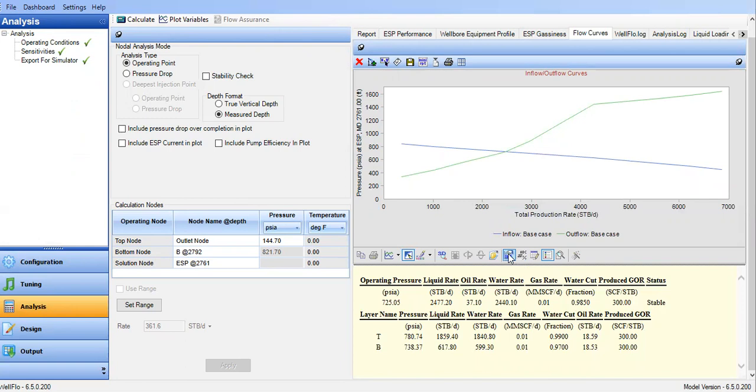Okay, so by combining the two reservoirs, we get improvement in oil rate. Previously, if I'm not mistaken, the oil rate was 23, because you have water cut of 0.99. And after you combine them and the new reservoir has lower water cut, you get at the end an oil rate of 337 with water cut of 0.985.